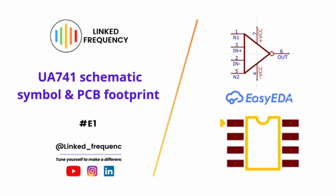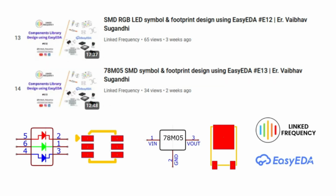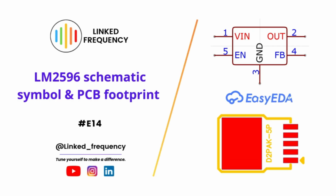From the 11th tutorial, we started with SMD components, starting with the MU-A741, which is an operational amplifier. The schematic symbol remains the same, but the PCB footprint is for the SMD component. That's where we learned how to use top layer copper pads for creating a PCB footprint with Cartesian geometry. SMD RGB LED and 78M05, which is the SMD version of 7805, are the most commonly used SMD components in electronic component design engineering. We also covered how to design a schematic symbol and PCB footprint for the LM2596, which uses a D2PAK PCB footprint with various dimensions available.